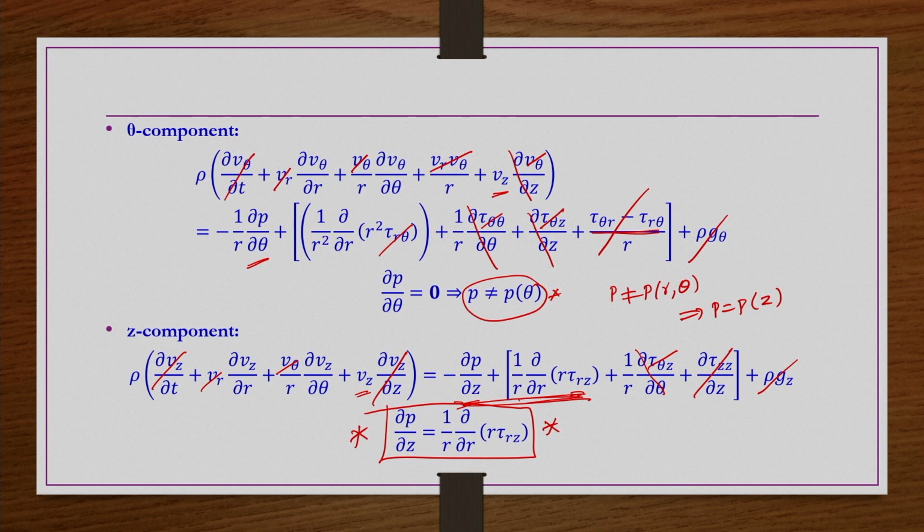Navier-Stokes equations are explicitly for Newtonian fluids, whereas Cauchy's momentum equations are generalized for any fluid, Newtonian or non-Newtonian. Only that in the place of tau, if you substitute the respective equation for the nature or rheology of the fluid, then that equation would be for that fluid.